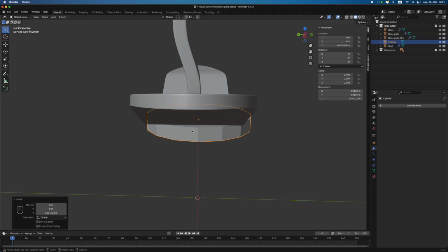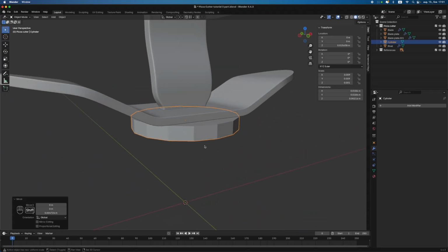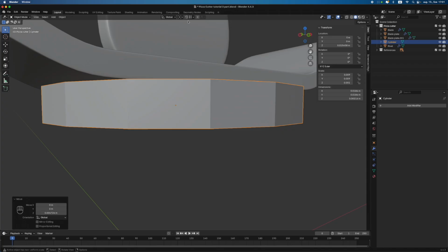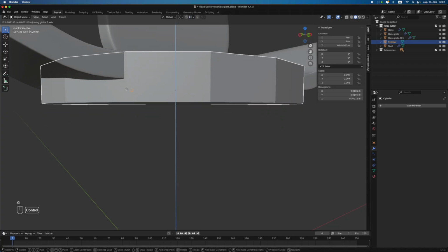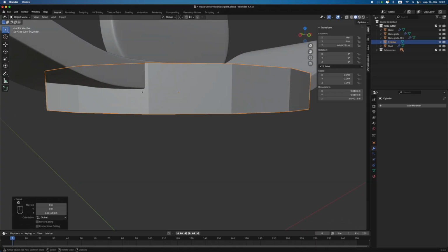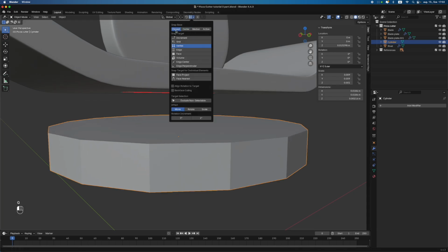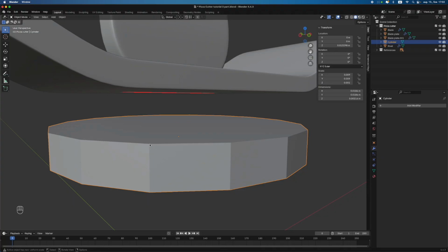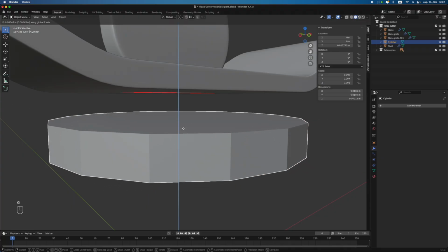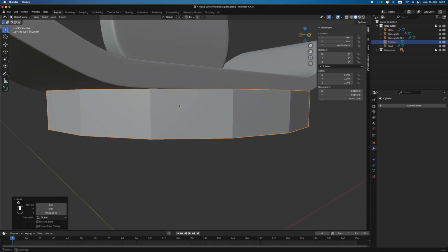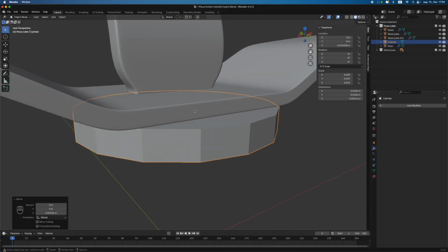If yours doesn't snap, for example, to the bottom vertex, you can change this center value. If I now press and put it here, it will jump to the center. The object's center will jump to the vertex. If we set it up like the closest point, which is this one, and this, the top face, will jump to the vertex that we are pointing at.